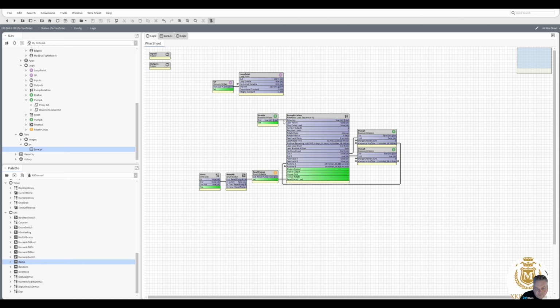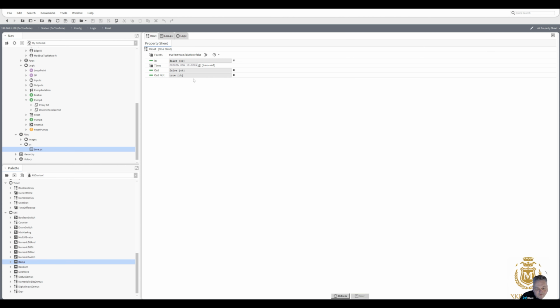So let's disable that. Let's enable it again. So this we're going to fault. And then this one we're going to fault. And then we do a fire. That's B, reset. And then when the fire goes off, which I've done for 10 seconds, 10 seconds is too long, you only need 5 seconds. And there's your A done. So let's just adjust that to 5 seconds. Reset. So that's your global reset.